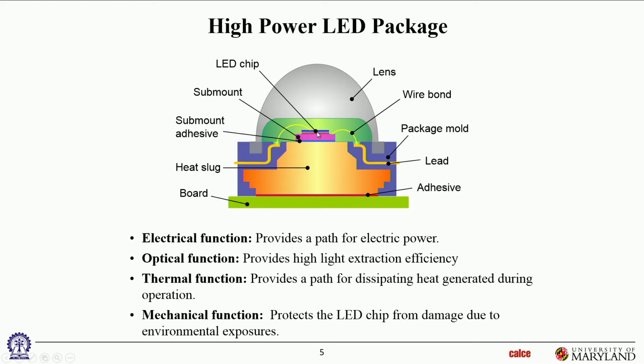And then we'll talk about a particular commercial white light technology that uses phosphors. They use the phosphor to convert blue light into white light, because the phosphor absorbs the photons and re-emits them as white light. That phosphor degrades over time. So what you bought as a white LED, or a warm white LED, slowly turns bluer and bluer because the phosphor is degrading. And then the lens also degrades, gets yellowish with time, because of this strong photo exposure, there's photo degradation of the polymer there.